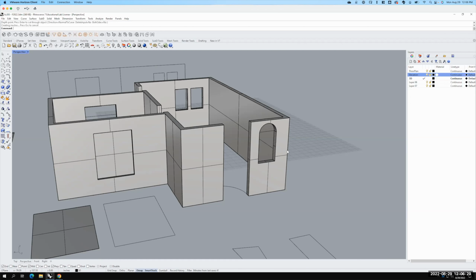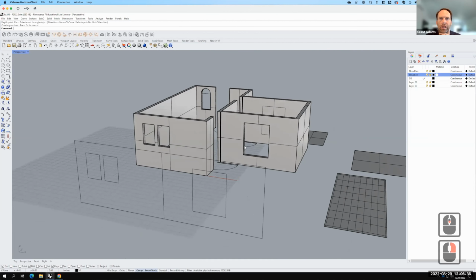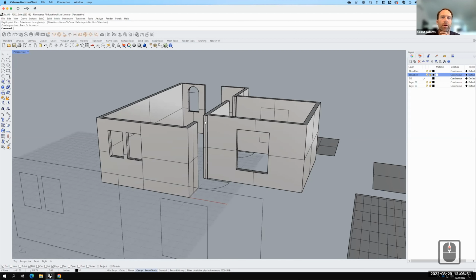Okay. So our goal here today is to extrude these walls, use the project command to project your elevation onto these surfaces, and then use the make hole or trim. Hopefully it's the make hole. I'd like you to get used to that as an operation to cut through your building, at least in a few spots. This is what we're looking for. When I'm done, I just need to do a screen capture of this. That's what you'll be turning in for your exercise 203.